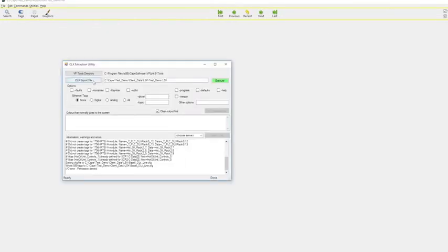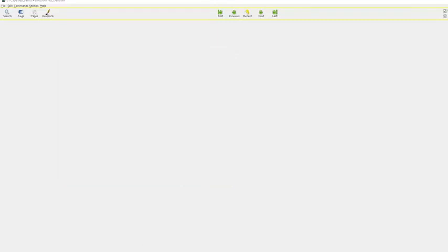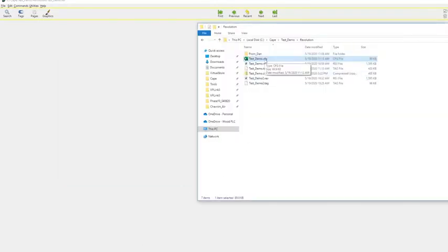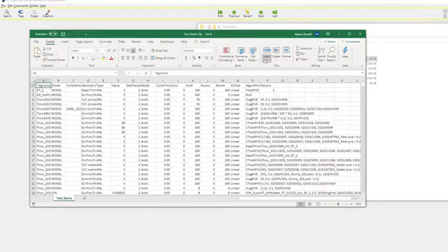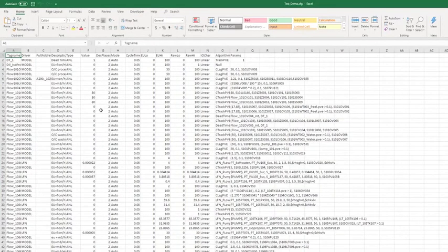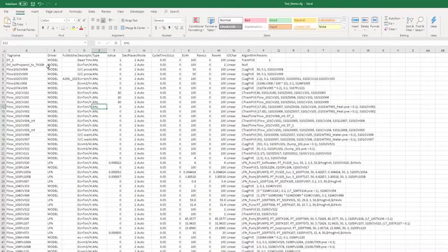For this Rockwell example, step 1 in this process is to save the ACD file as an L5X file. The demo shows the extraction program go through the process of automatically extracting the relevant data from the control system file. The resulting extracted file is a config file that can be readily opened in Microsoft Excel. The extraction process gives us the control system tags in an easy-to-read and editable Excel format. From here we can review the tags, add extra details and manipulate the parameters and algorithms.